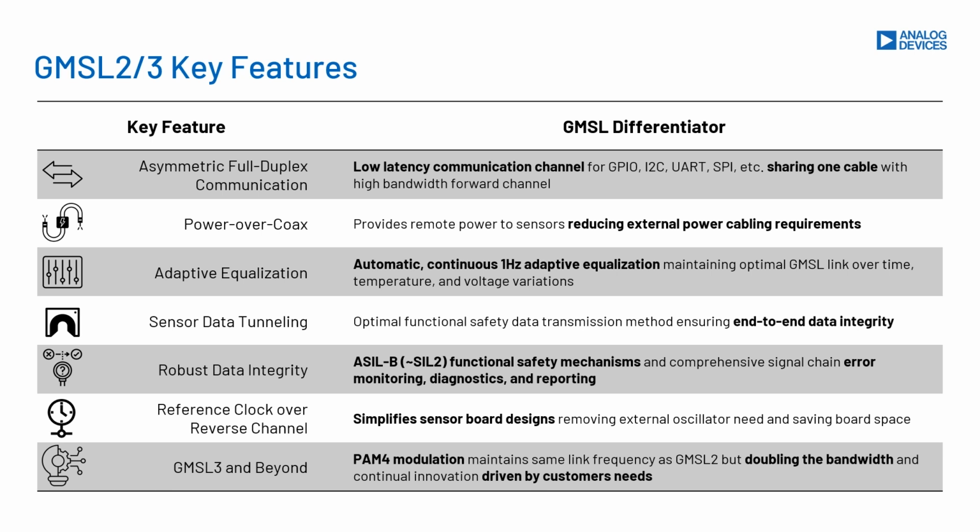As mentioned in the previous slide, GMSL2 and 3 SerDes are all ASIL-B qualified, which is equivalent to SIL2 in some industrial applications. GMSL devices have comprehensive error monitoring, diagnostics, and reporting features to help functional safe design on the system level.